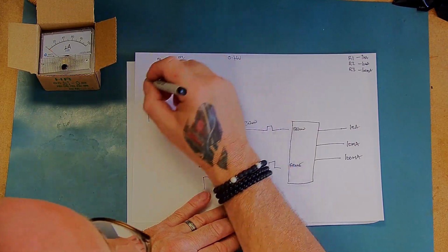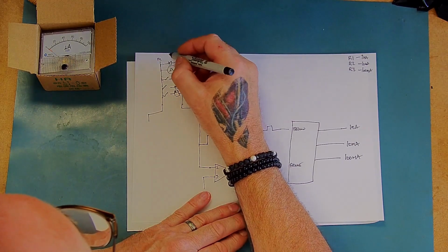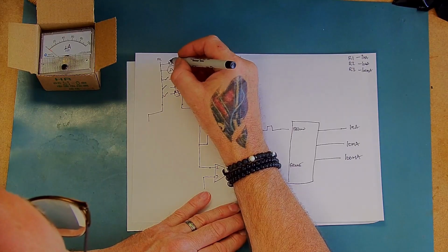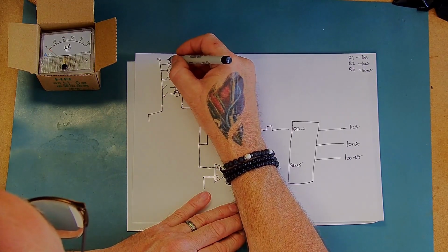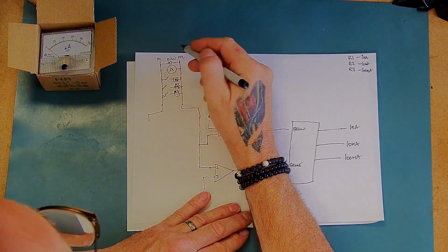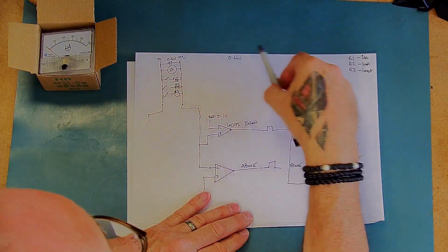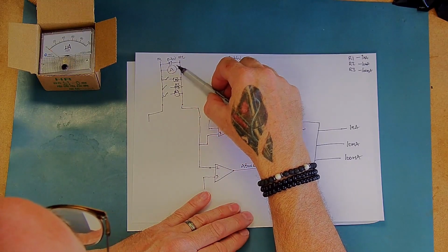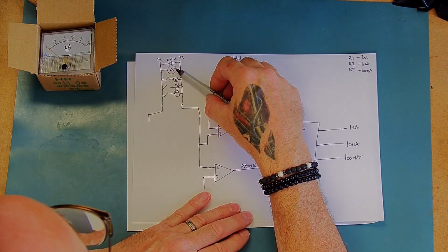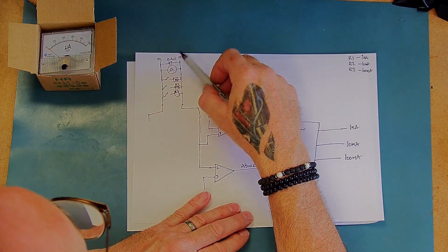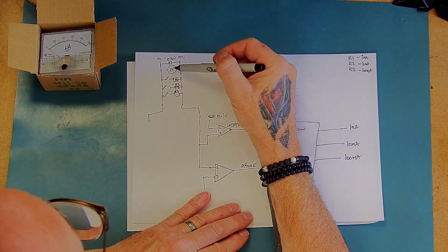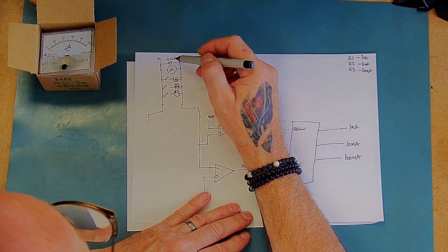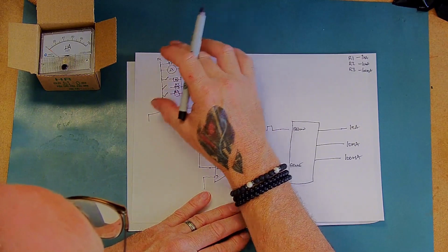We know that this needs 0.46 volts for full scale deflection. If we just put a diode across the meter, we can actually protect it because it will clamp the maximum voltage to about 0.6 of a volt. So even if we get this system totally wrong and we try to put 100 milliamps through a 10 microamp meter, which would normally probably blow the meter up, burn the coil out inside the meter, we can actually put a clamping voltage of 0.6 of a volt on that, so it will not do that.